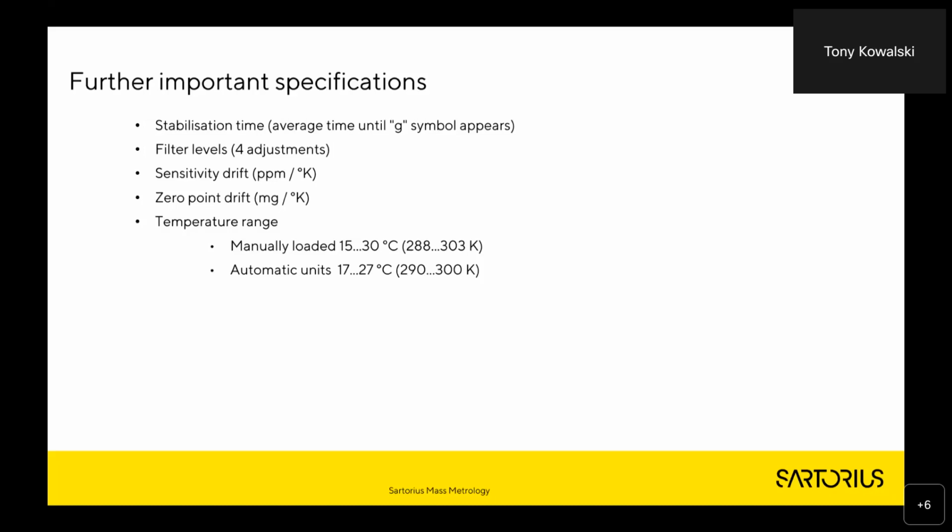Quite often in mass metrology, we use this stability indicator to give us the moment when the comparator is more or less stable. If you have a comparator with a glass draft shield and maybe 4, 5, or 6 decimal places, when the door closes or you've taken your hand out, there could be just a little bit of air movement.